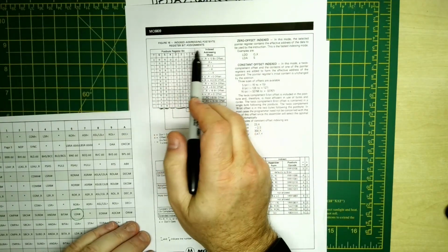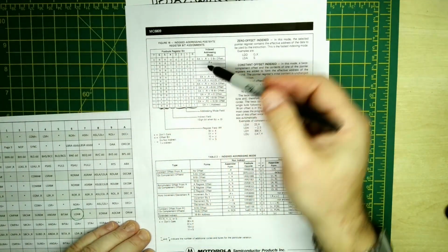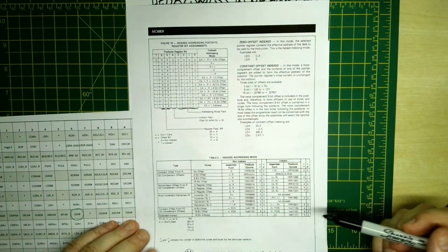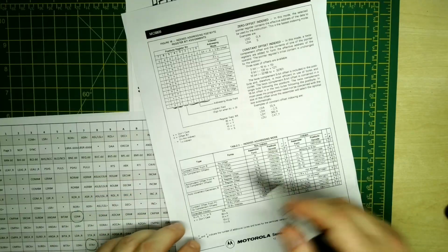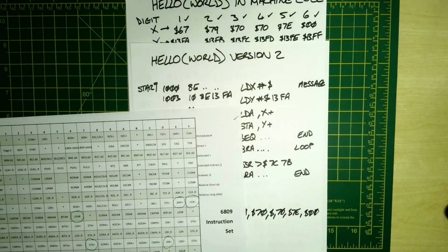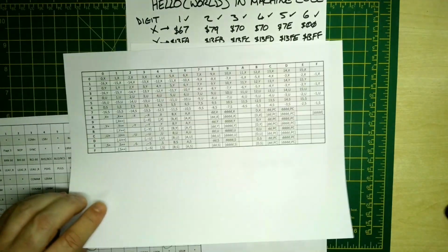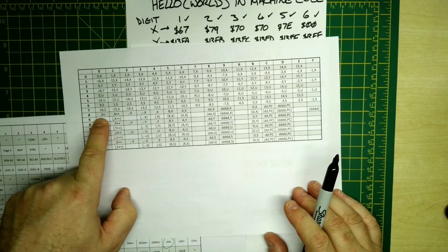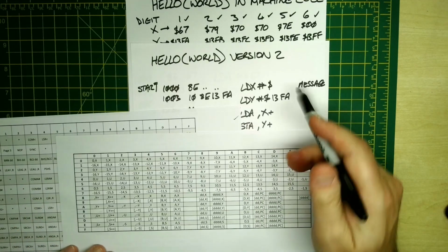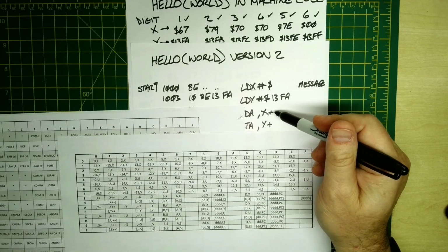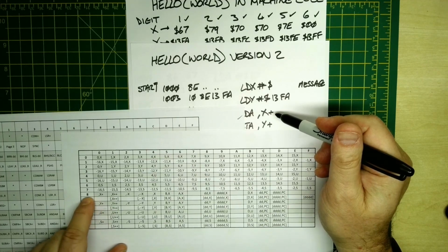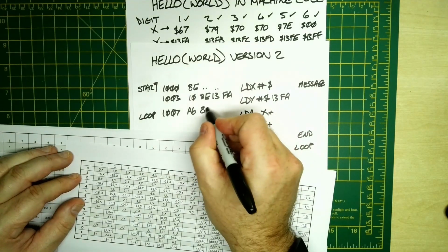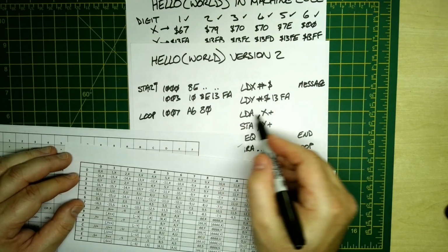This shows that there's a post byte that tells us which register to use and which of the many addressing modes we're going to use. Now, because this is quite complicated to work out, what I've got here is one where we've already worked it all out, and it's part of the same coding grid. So in this particular case, we want X and then increment X after use, so post increment, and that happens to be 80. So we've got 80. Okay, so that's load A with X.